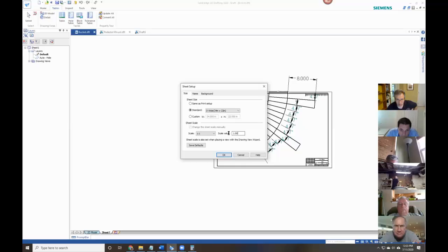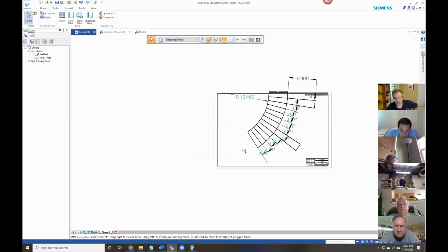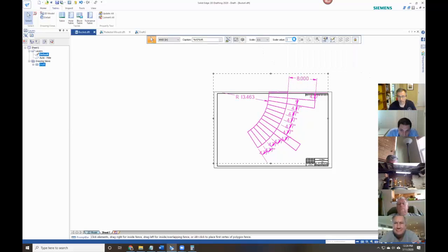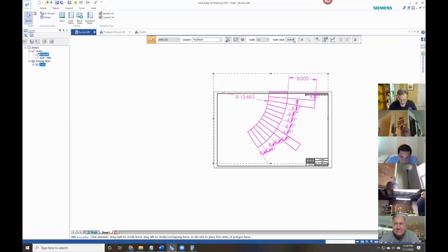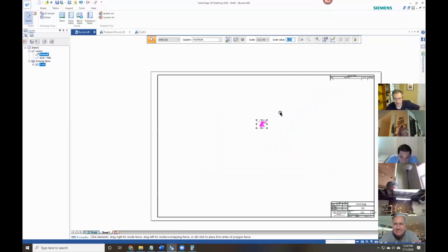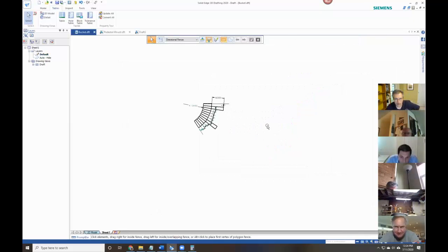I can paste that in there. And that didn't work. Oh, all right, never mind. That's not how it's done. You select what you pull in, and you put the scale value in here. That didn't work. It won't let me paste it. So I have to hand type it. What was it? 0, 4, and a bunch of 6s? 0416. Yeah. All right, so now that's to 1 to 24 scale.